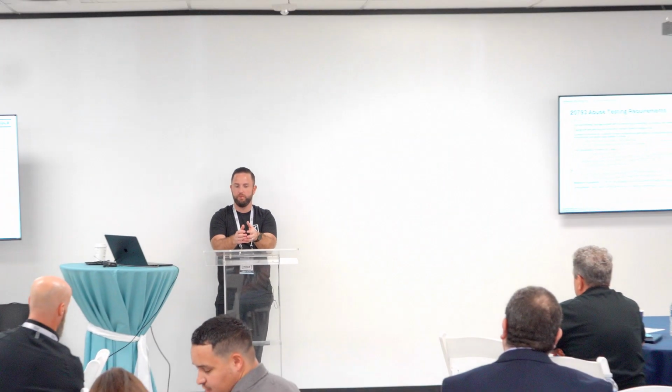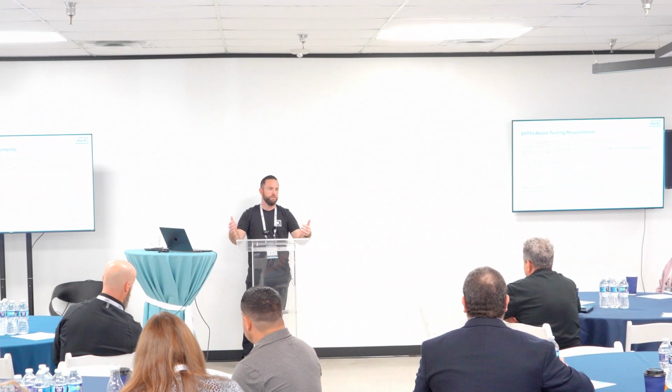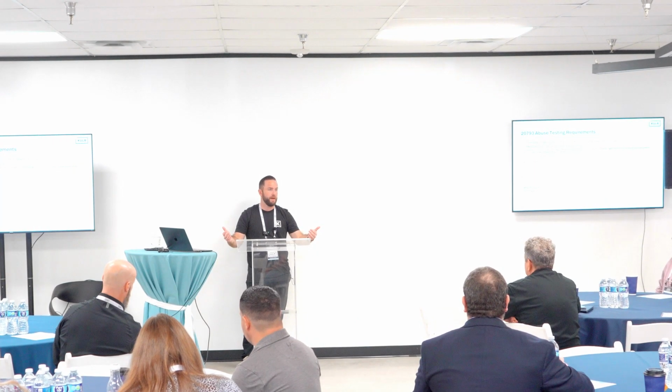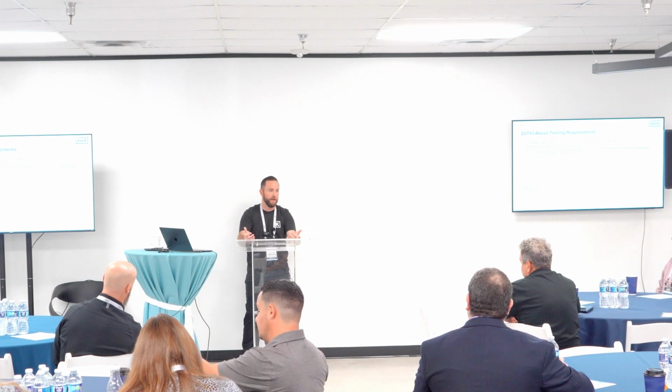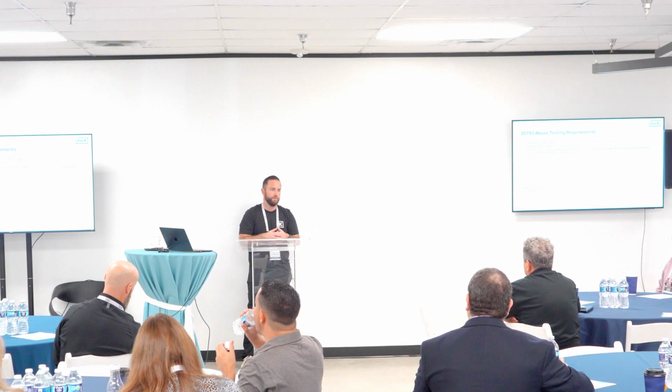So a lot of these designs, we're talking about marginal success here. It's a game of inches, right? Especially when you get to some of those super energy dense packs. And so you don't want to just bake out a trigger cell to 150, 180 degrees Celsius and allow those neighbor cells to just soak in all that heat, because now you've biased what would be a perfectly good test and a perfectly good design to fail propagation in a way that's completely unnatural from what you would see in a field failure event.